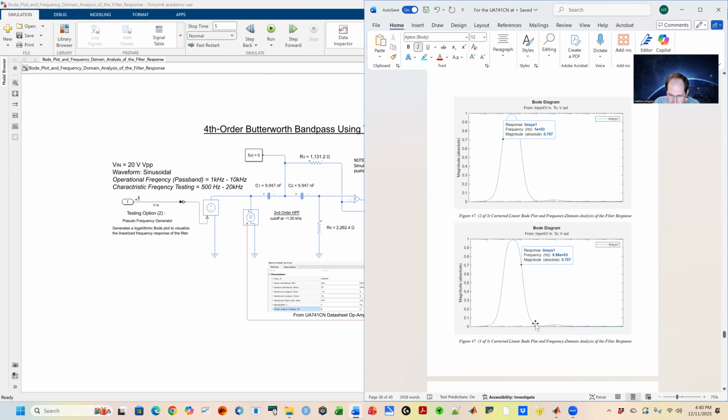And the one on the right side is called the high frequency attenuation region. These two slopes are what define the stop bands I was talking about a minute ago. So the lower and upper attenuation regions define the stop bands, and that in turn determines the frequencies the filter rejects.